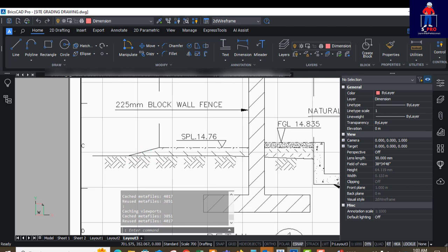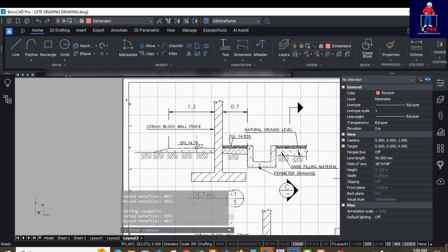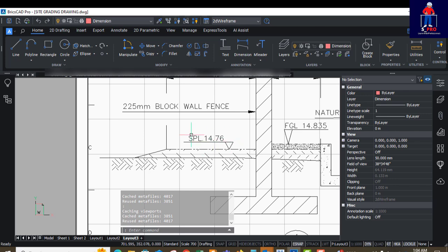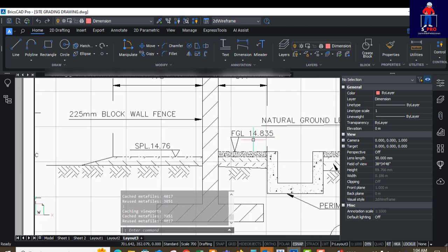And I told you that we raise the facility up. So this is the demonstration, the drawing of how the site is being raised. We now put the site preparation level. The levels are being labeled very well, and how this place is being sloped. See, the finished grade level is higher than the site preparation level by 75 mm.